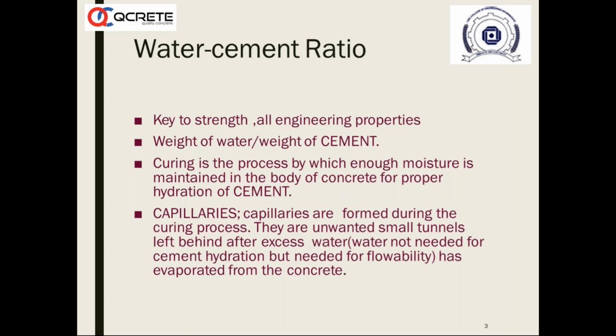So what happens if the water is evaporating? If the water is evaporating, it leaves behind small tubes or tunnels in the body of concrete, which are called capillaries. So the more water you add into the body of concrete during mixing or making of concrete, you are giving an opportunity for more water to exist in the body of concrete in the initial stages, and you are giving an opportunity for that excess water to evaporate.